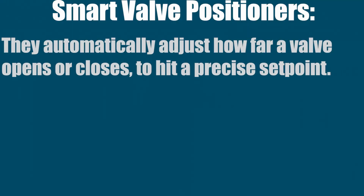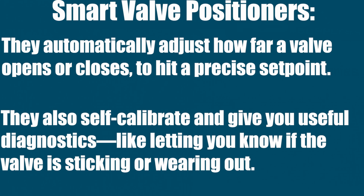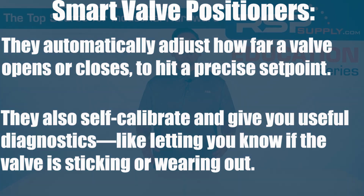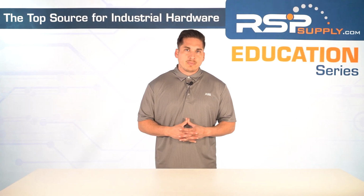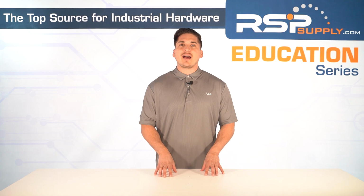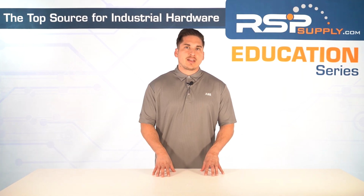Then you also have smart valve positioners. They automatically adjust how far a valve opens or closes to hit a precise set point. They also self-calibrate and give you useful diagnostics, like letting you know if the valve is sticking or wearing out. Some examples: Fisher makes the DVC, a digital valve controller. It's a popular choice in oil and gas. Siemens makes the SIPART PS2. It's widely used in chemical plants.